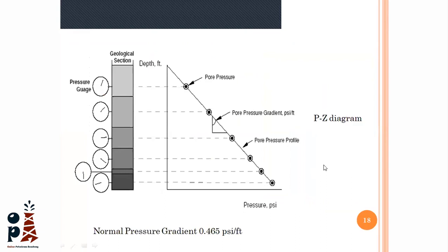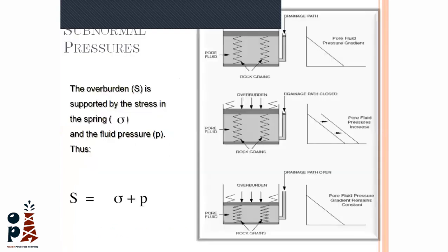Guys, here I talk about the formation pressure and the fracture pressure, and now the time is to talk deeply about these two concepts. The pore pressure, as I told you, is a function of the overlying rocks' weight. So it makes sense that when we go down, the pore pressure will increase. The pore pressure is calculated worldwide, with a lot of data gathered from wells around the world. So we get a worldwide trend of the pore pressure, where the normal pressure gradient is 0.465. This is from a lot of data. Okay, so let's see this one to understand the effects of the overburden pressure.